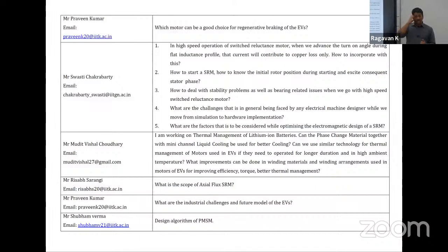That will basically be the ID of your rotor and the thickness of your poles, which will dictate how much flux density and what saturation levels you're going to get. Your system tends to get more non-linear as you go forward. So you have to make sure those localized hotspots are either managed or designed appropriately. Flux barriers in SRMs are somewhat tricky. They can arguably be done, but I haven't seen anybody who's done it really well. I don't think so, right?